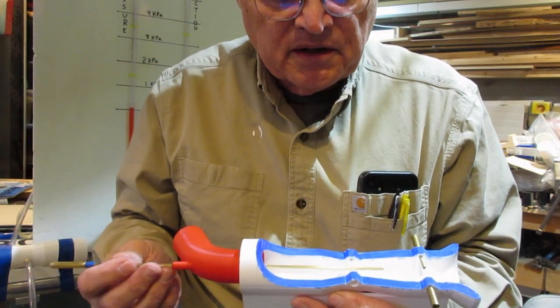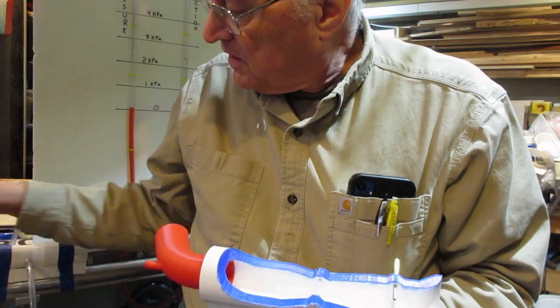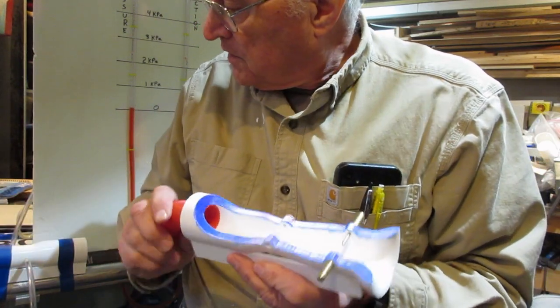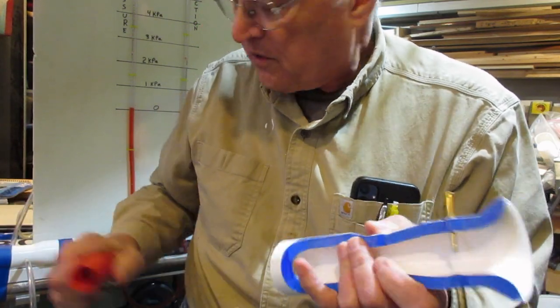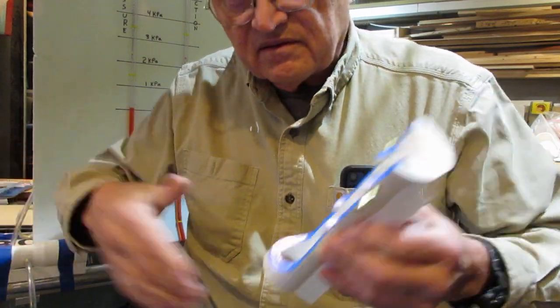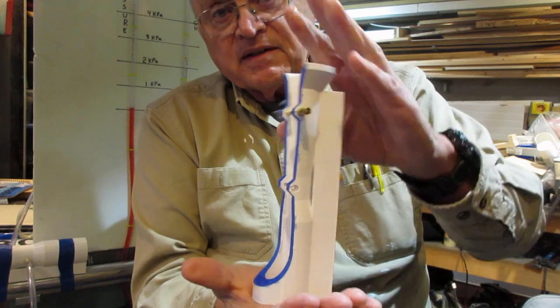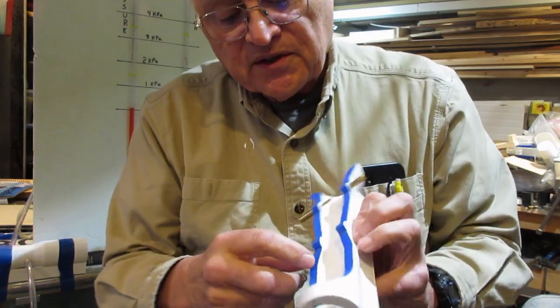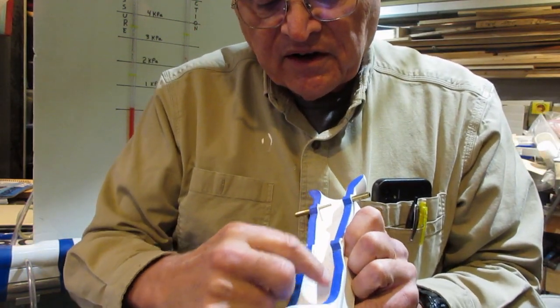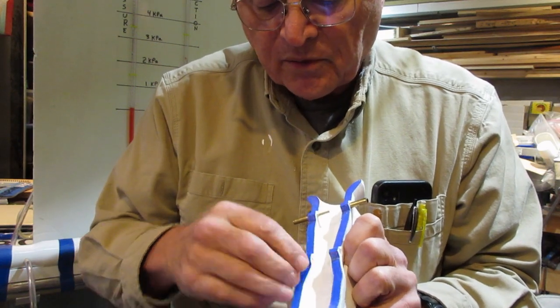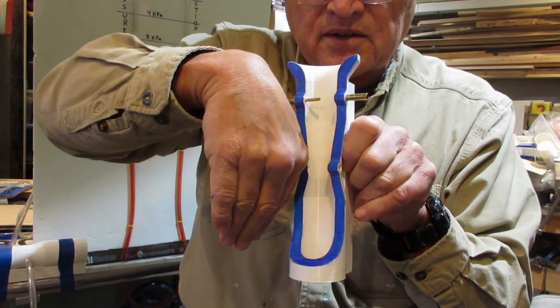One problem here is in this Venturi, to make it easy to 3D print on normal typical size printers, standing up, I had to limit the height. So this diverging area here behind the Venturi is way too steep, way too angled, okay?